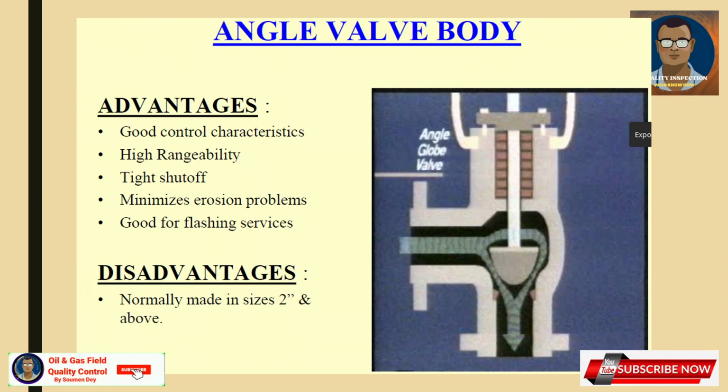Angle valve body. Advantages: good control characteristics, high rangeability, tight shutoff, minimizes erosion problem, good for flashing services. Disadvantages: normally made in sizes 2 inch and above.